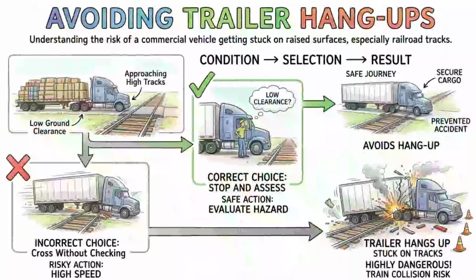Understanding how to recover from a skid is a critical safety skill for the exam. The most common type of skid is a drive wheel braking skid, which happens when you brake too hard on a slippery surface and the rear wheels lock up. To recover from this type of skid, you must instantly take your foot off the brake pedal to let the rear wheels start rolling again. Once the wheels regain traction, you should steer quickly in the direction you want the vehicle to go. Never try to accelerate out of a braking skid, as it will only make the situation worse.